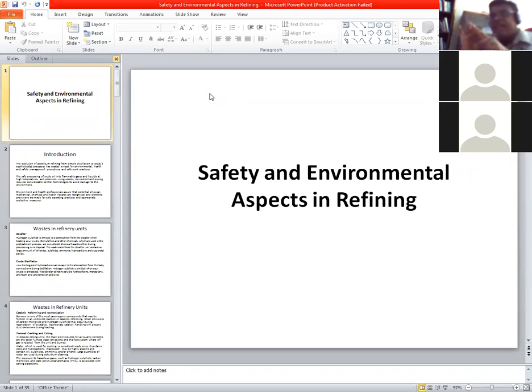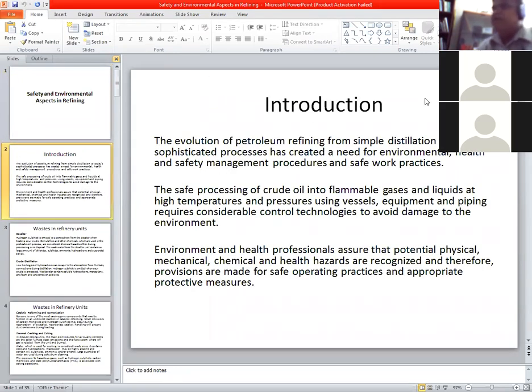So VCE, as I told, is vapor cloud explosion, and the other is boiling liquid expanding vapor explosion. These are very common explosions happening in the petroleum industry, so you have to be very careful about that. So these are the main things I want as the concept of today's lecture.